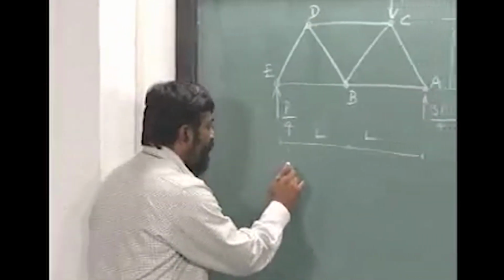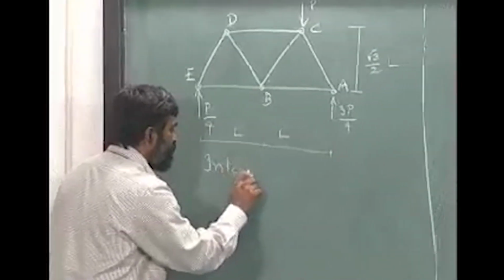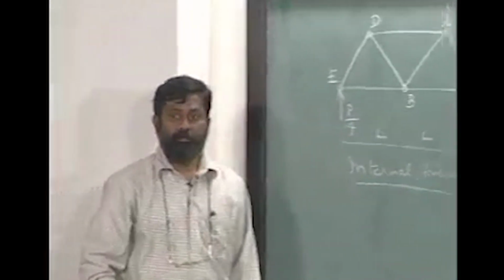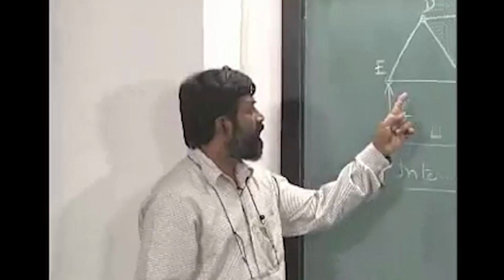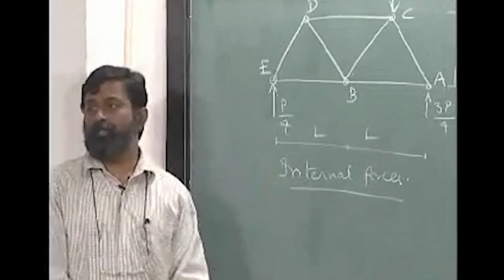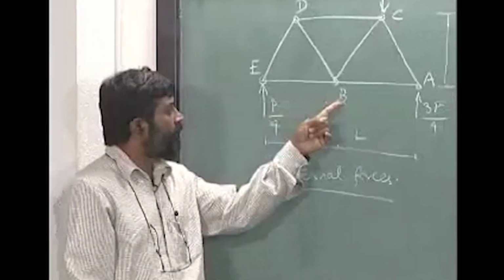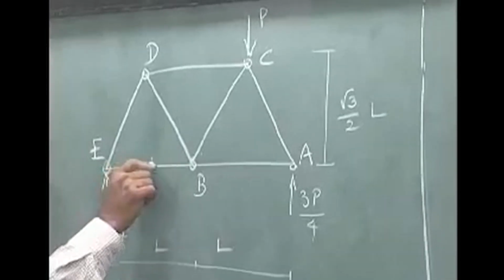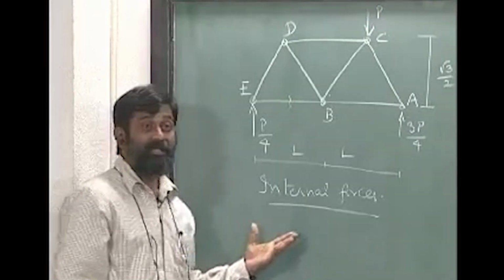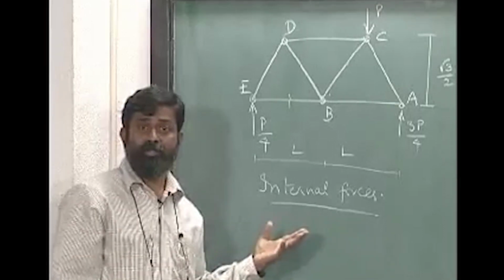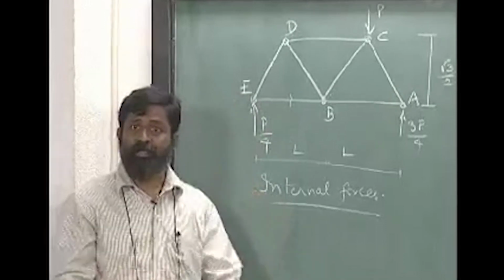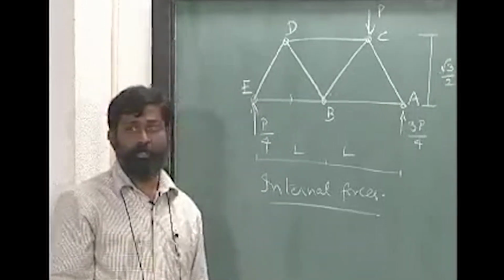As a first step to finding out internal forces, we know very well that we have to cut any one of those members for which we want to find out the internal forces. Supposing I want to find out the internal force in BE, I need to cut that particular member. Okay. So as a first step to solve for internal forces, we need to cut, and let us cut and see if we can find out how to solve for internal forces.